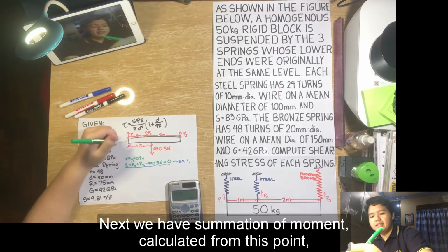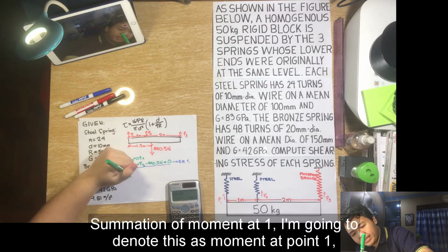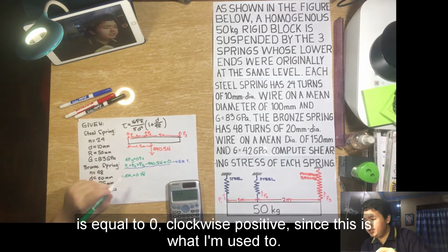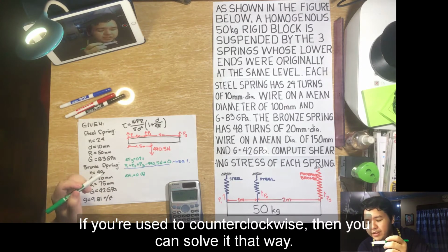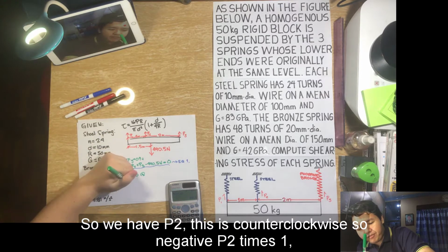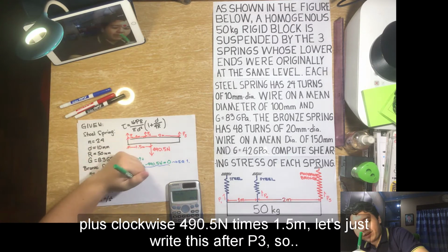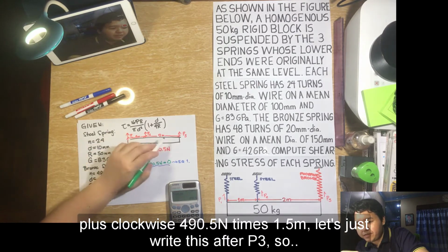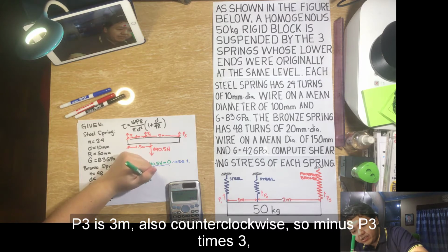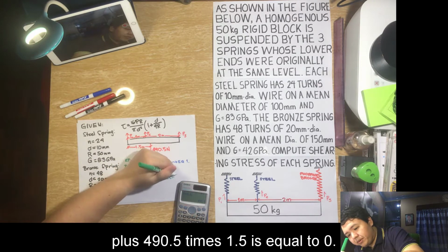Next, we have the summation of moments calculated from this point, which is the point of the first steel spring. So the summation of moments at point 1 is equal to 0, clockwise positive, since this is what I'm used to. If you're used to counterclockwise, then you can solve it that way. So we have P2. This is counterclockwise, so negative P2 times 1, plus clockwise for 490.5 newtons times 1.5 meters. Let's just write this after P3. P3 is 3 meters away, also counterclockwise. So minus P3 times 3, plus 490.5 times 1.5 is equal to 0.